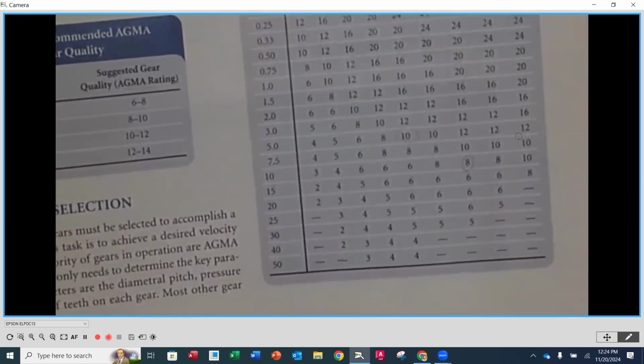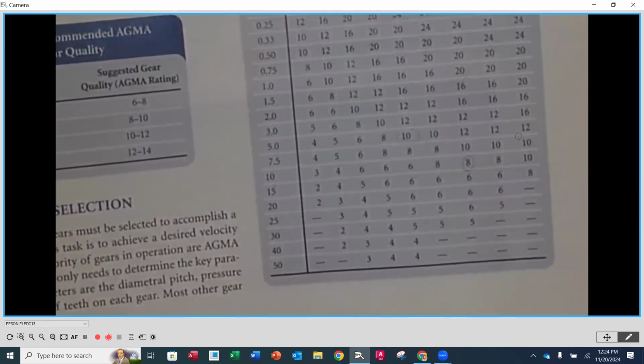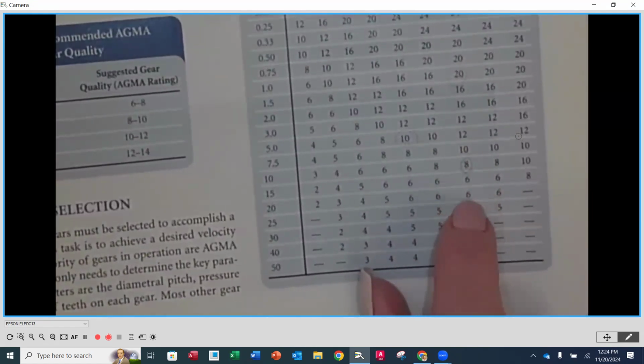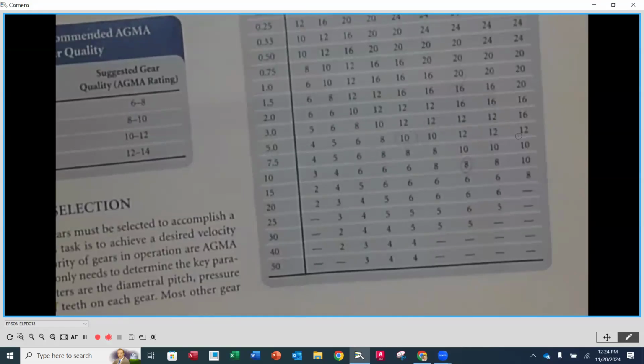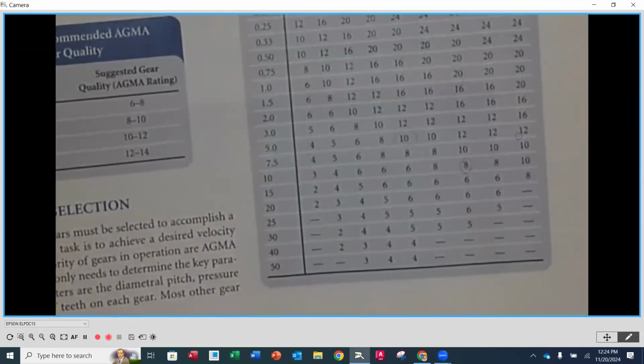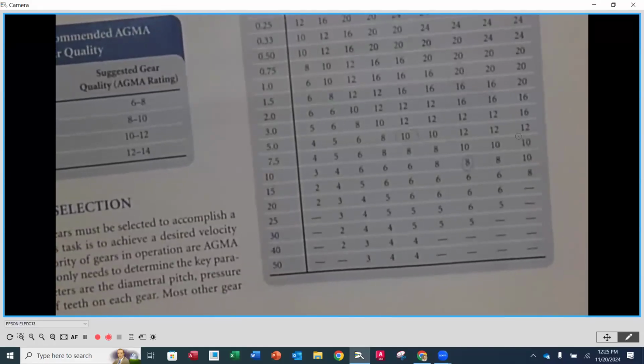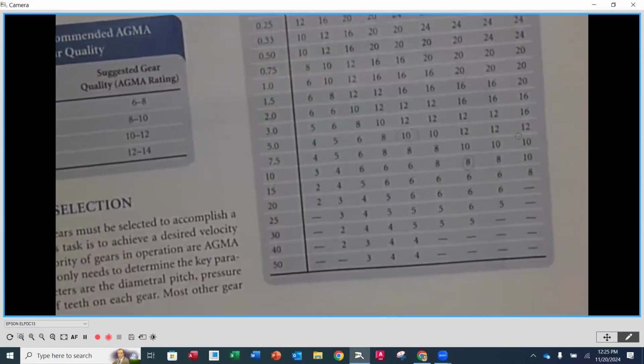So what you end up finding out in that process is what are the stresses that are generated, and then you compare those back to what are the stresses that it can actually take. And in some cases, if you find that the stresses are too high with this value, then you would go up a size or 2 on your diametral pitch, meaning you want bigger teeth because you have stresses that are too high. So what I'm trying to say here is this is the place to start. In kinematics, we're not worried about forces or stresses or those pitting stresses or those bending stresses. There's more to finishing up this design, okay, that's my point here. And you will finish those up when you're in design of machine elements.